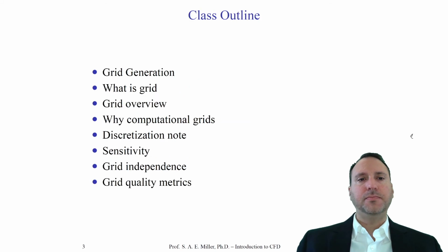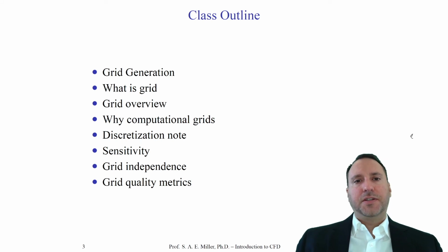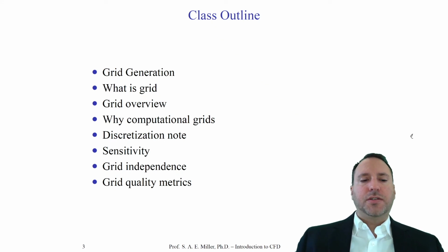This is mainly the type of equations we're looking at this class, which is a nonlinear set of partial differential equations. With the Navier-Stokes equations, or any type of PDE and its associated numerical solution, we have to discretize them. Why? Because we're solving them on digital computers. So we have to create a computational grid. We'll first look and define what is a computational grid in this class. Next, we'll look at an overview of the computational grids and classify different types.